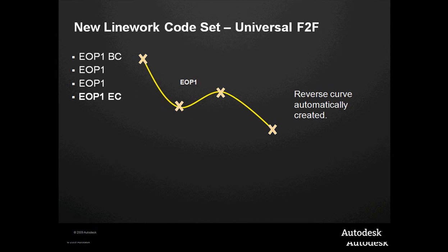Question? Yes, sir. The question on that is whether the figure that's created is 2D or 3D. The actual object that's created is a survey figure line, and it's kind of a glorified 3D polyline. I say glorified 3D polyline in that it maintains elevation, and on the curves, it will warp the curve down and around. But we can select that line, and we can ask the system, I want to see grades, and it will show me grades for every point all the way along that.